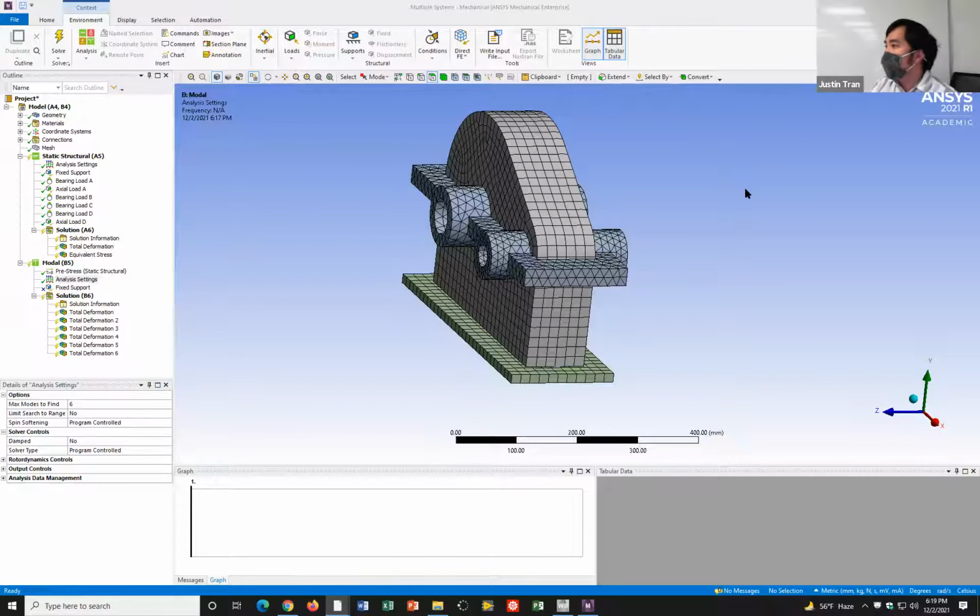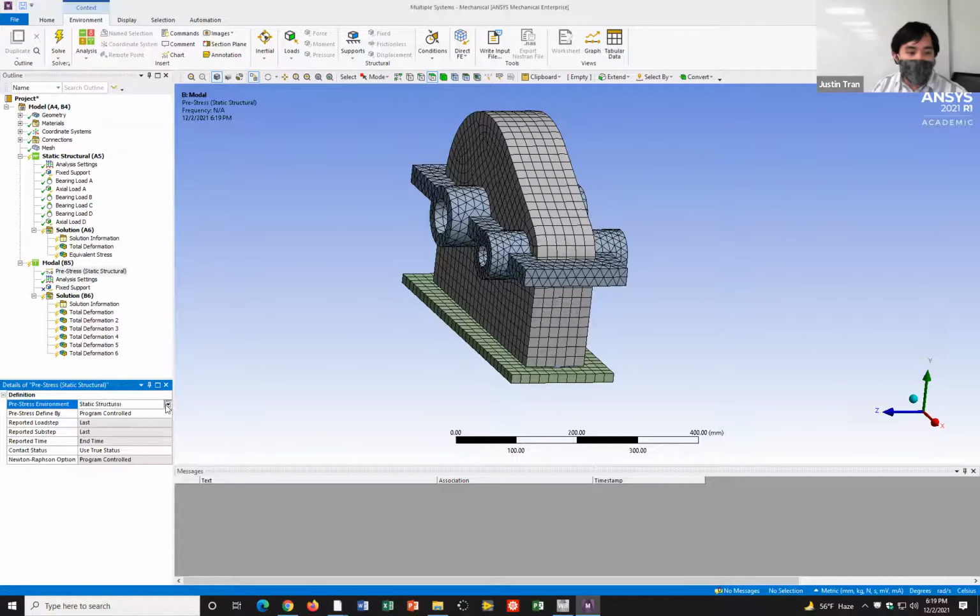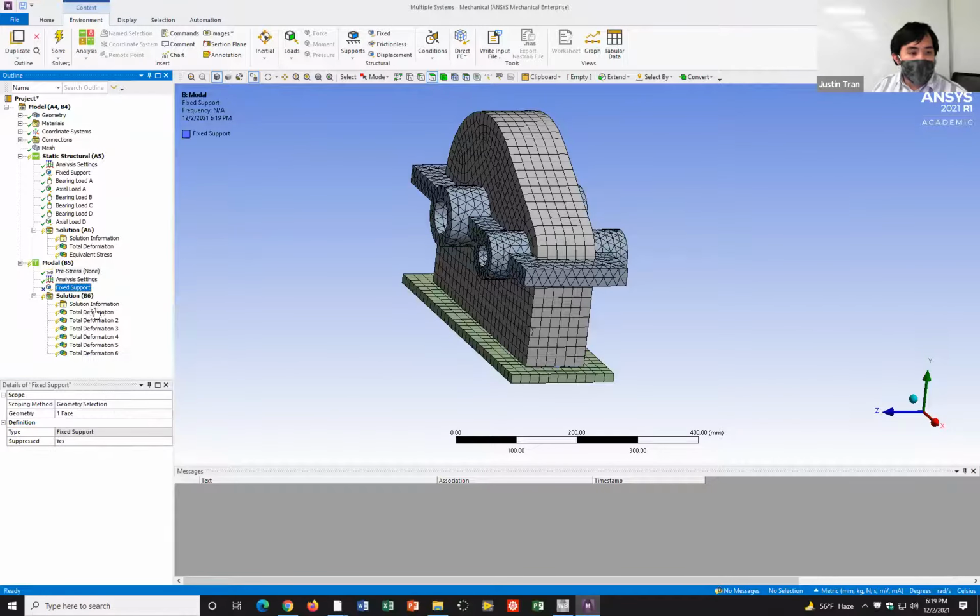So instead of having it much higher or much lower, does it make a difference? You definitely want the forcing frequency to be much lower than your fundamental frequency. For this particular case, where the fundamental frequency was 315 hertz, I would only feel good about the structure if the forcing frequency was like 150 hertz. That means the maximum gear speed is not even going to get close to resonance.